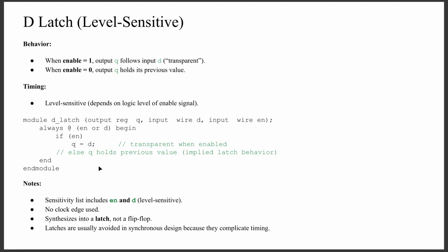Note, the sensitivity list includes enable and D. No edge clock is used. It synthesizes into a latch, not a flip-flop, and latches are usually avoided in synchronous design because they complicate timing.